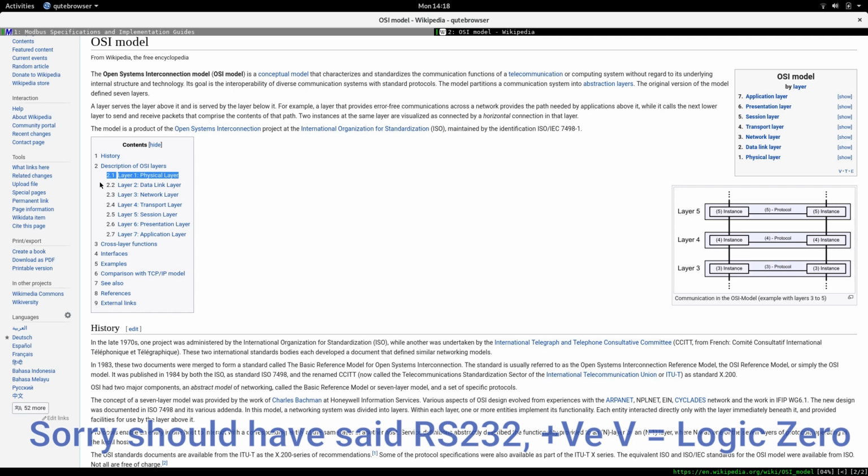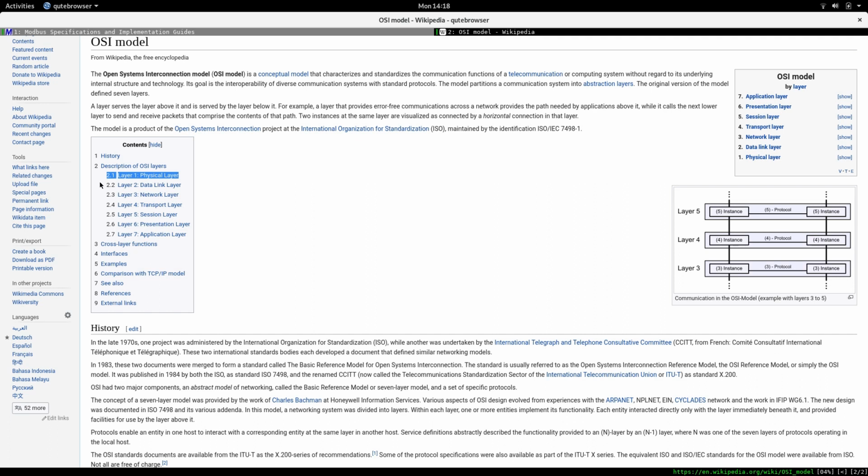In RS485, a high voltage is the idle state, and that's also counterintuitively a logic level 0. And then when it falls down to 0 volts on the line, that's a logic 1. And that's just the physical layer, the difference between two protocol implementations on a physical layer.